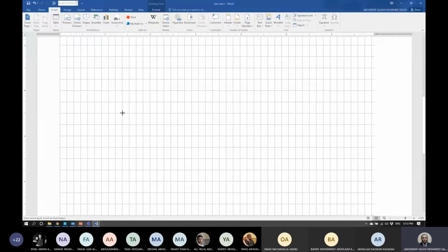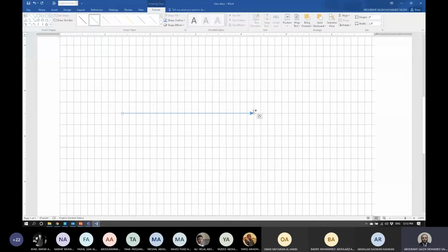If we have, guys, the phasor diagram at lagging condition, so this is V terminal, and assume IA in the beginning is lagging like that. So this is IA, and jIAXS should be perpendicular to this vector. So neglecting RA, guys. Okay, so this is now jIAXS, approximately 90 degrees, and finally this will be the vector of EF. Guys, is it clear?